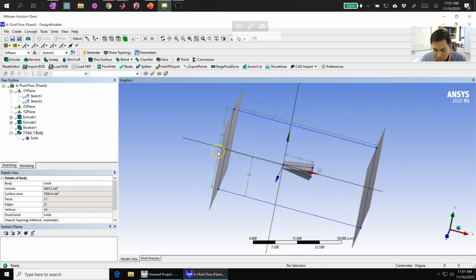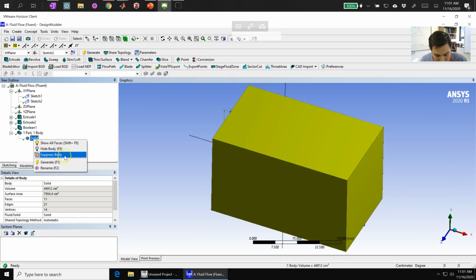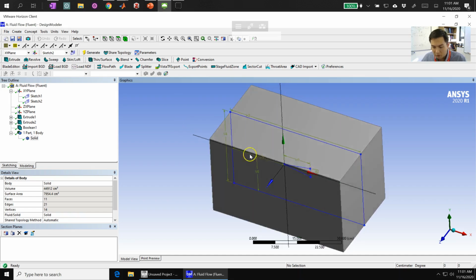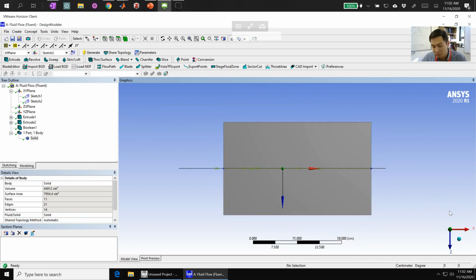All right, so how can we tell if we've actually been successful in doing this? Well, we go back to our base cube or base rectangular prism. And now what we can do is we can do a slice or section view. So if we go to the top of our box, we can click here on this sort of half filled in rectangle which says new section plane. And what you can do is you can just draw 2 points, and that will cut your geometry in half so we can see what's going on beneath.